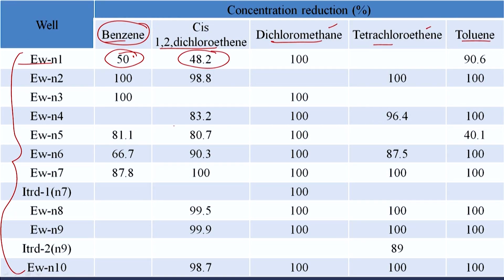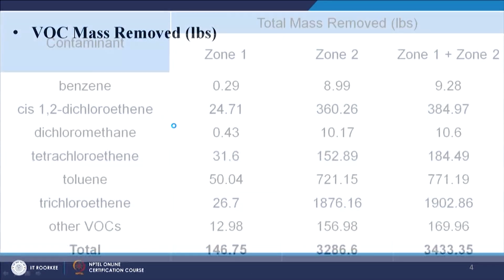But in general, as you look at this particular data, you see that the removal percentage is pretty good. Again, keep in mind that these are hydrophobic compounds, and pump and treat or such mechanisms typically will not work out here. So, let us look at the total mass that was removed.